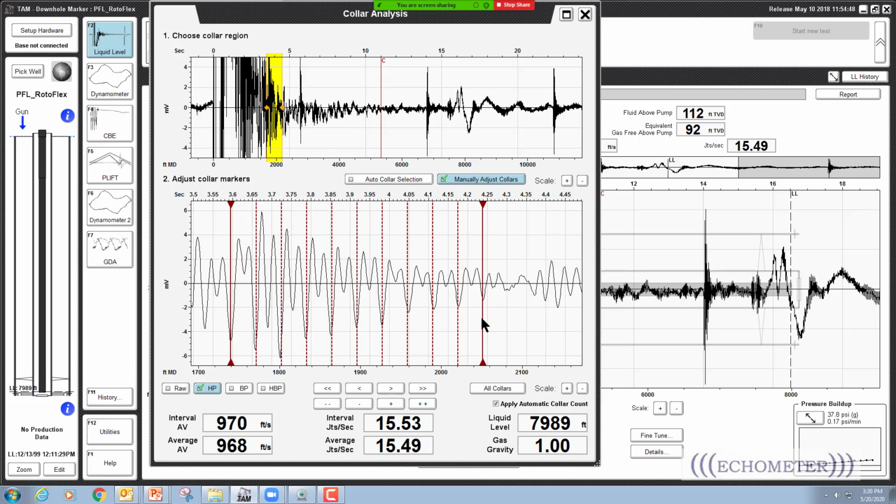Now if you have a compact gas gun, you could do an implosion shot or an explosion shot because it's not unusual to have nitrogen gas to charge a compact gas gun to a pressure of more than 1,000 pounds of pressure. But probably we'd do an implosion shot. It's going to blow some debris into the gas gun and potentially make us take the gun apart and replace an O-ring because it might get cut with some sand.